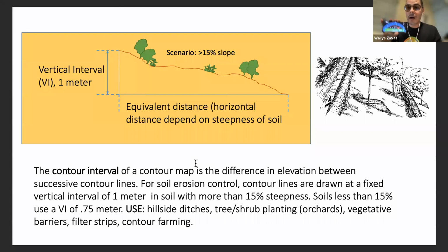Then that person will move to the upper part of the slope, and then you in the bottom part of the slope, you will point to that point, to the nose of the person. And when you find it, you look how many degrees or how many percentage this is indicating. And it's an easy way to measure the slope. But as I mentioned, I will share with you more information of other simple tools you can use to measure your steepness on the field, right?